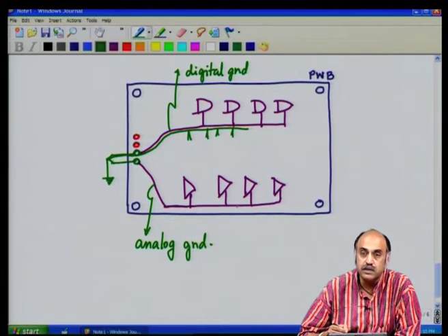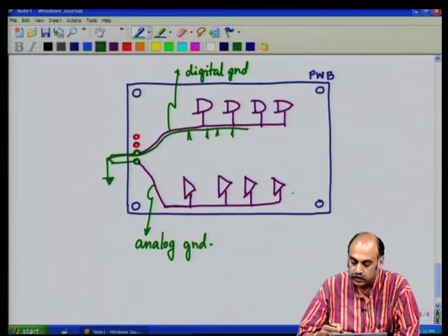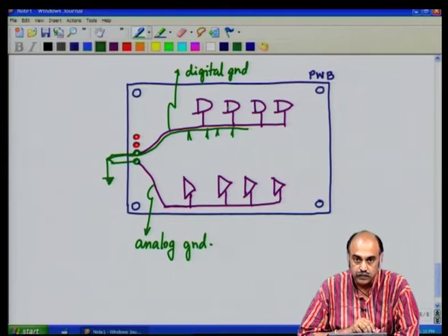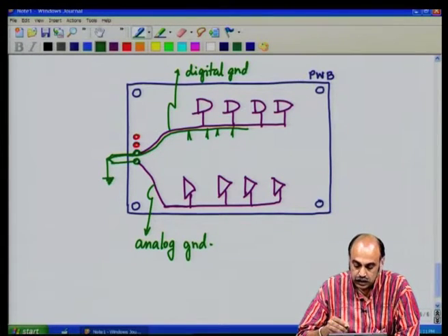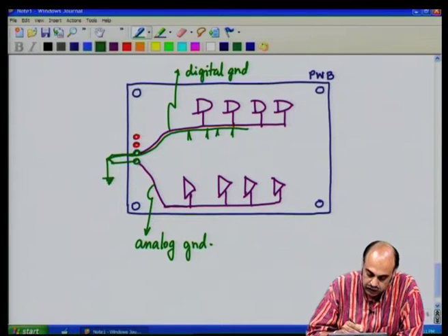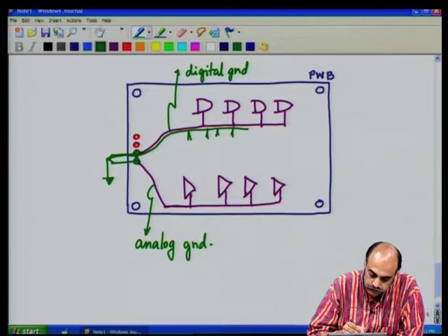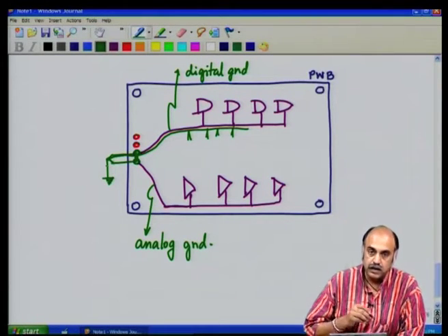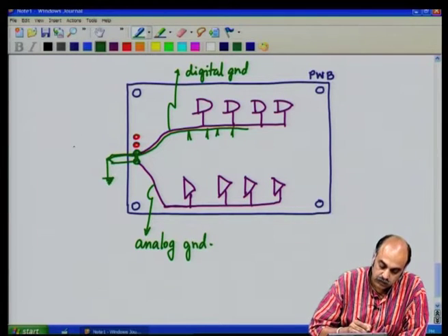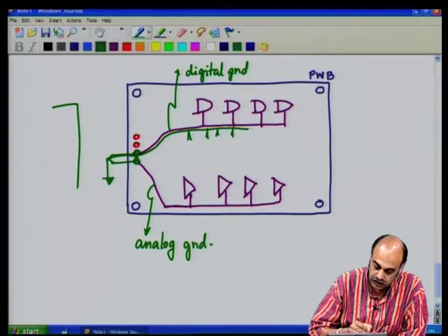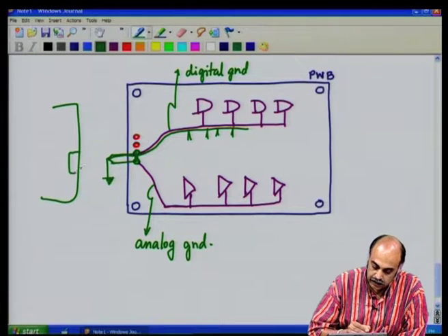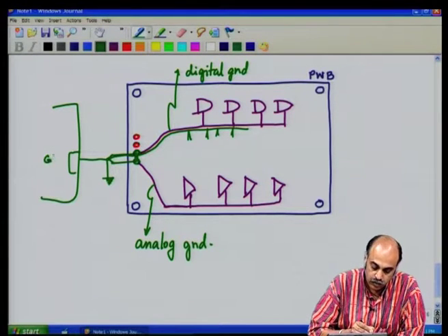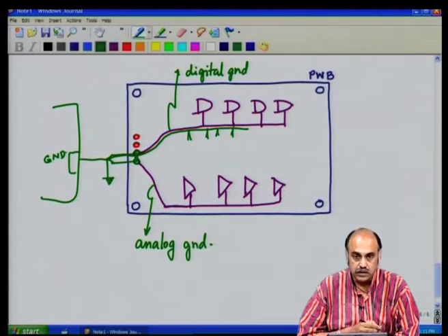Analog circuits are very sensitive to ground instability, and you can have a very quick deterioration in the performance if you make connections of the digital and the analog grounds within the PCB. At most you can connect it here at this point. Okay. But if the power supply board is still further somewhere here, you can connect it at that point if that is the most stable ground reference in your whole system. Okay. So, this is a very important aspect.